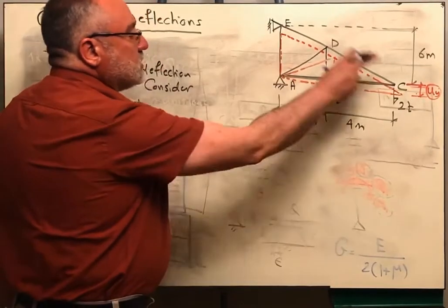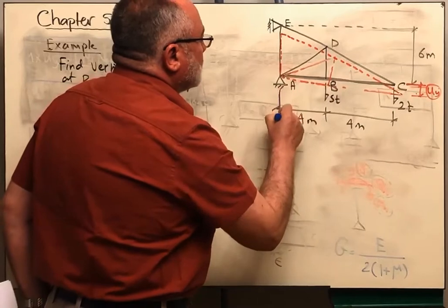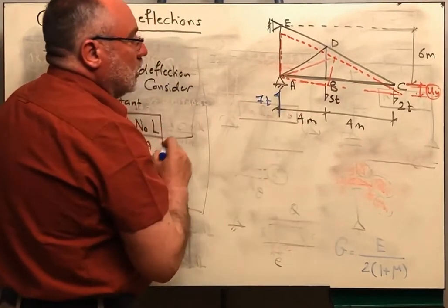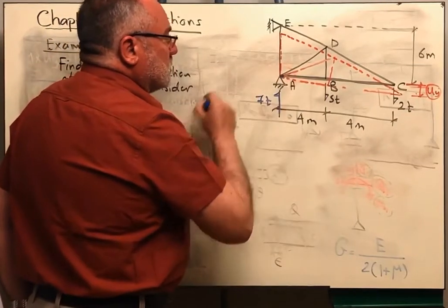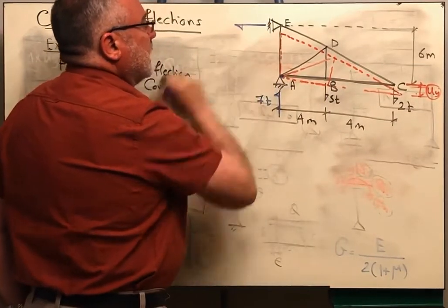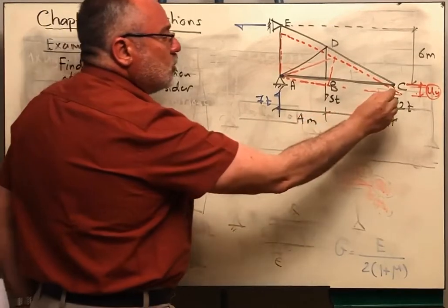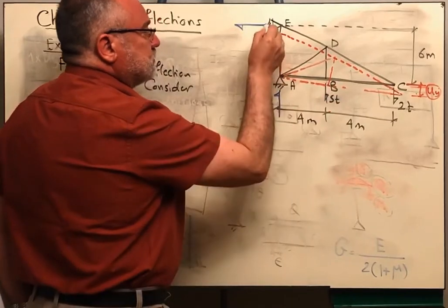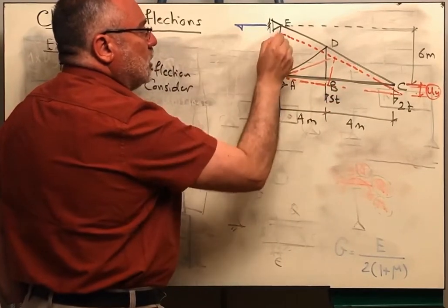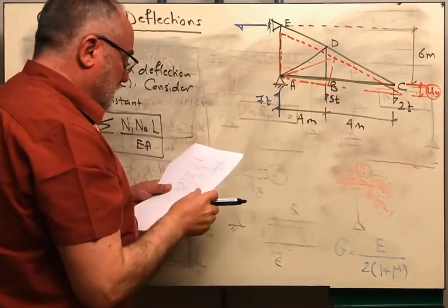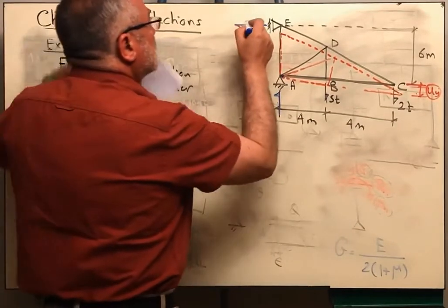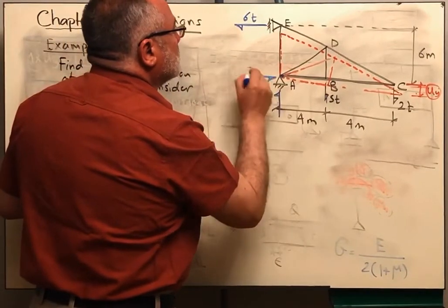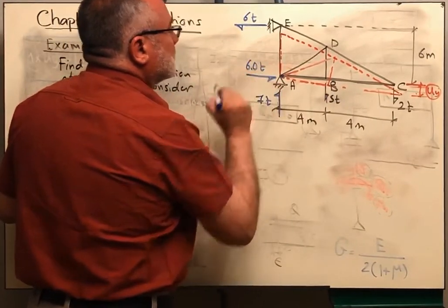we are going to solve this truss. We have a vertical reaction here. From sigma Fy equal to 0, this will be 7 ton. You can take moments about this point to determine the other reaction. You are going to have 2 multiplied by 8 and 5 multiplied by 4 equal to the reaction multiplied by its distance, which is 6. From there we get this 6 tons.